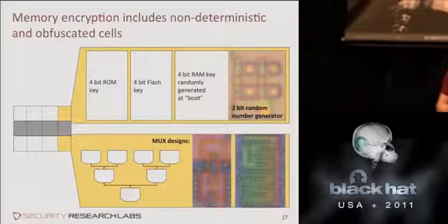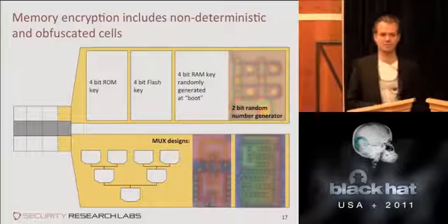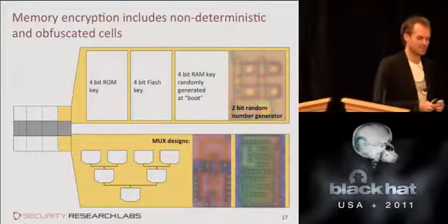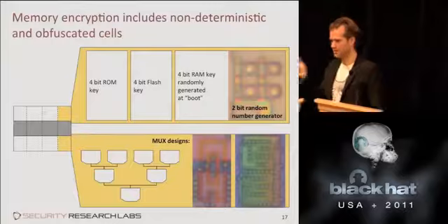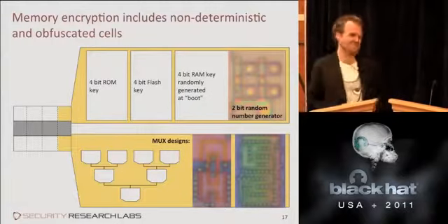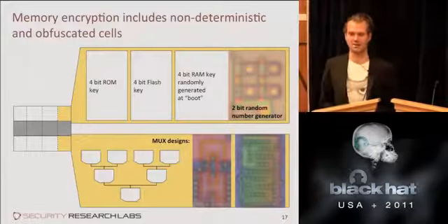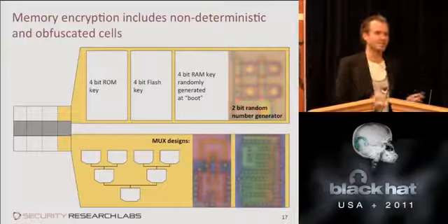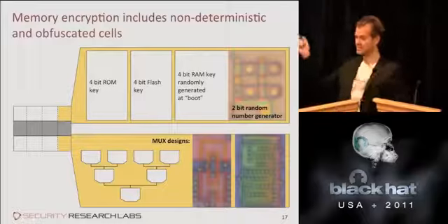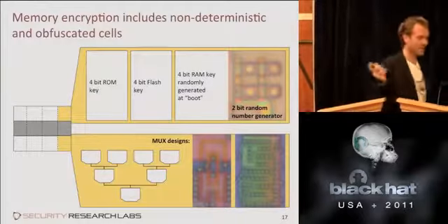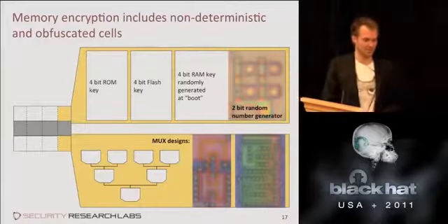And then one last thing to point out here. They did, as I said before, do a good bit of randomization of the gates, or obfuscation of the gates. Usually when you see a simple gate like a MUX in these cases, you can immediately tell what it is. Well, after looking at the silicon zoo, you can, each of you. However, in this case, that's not true. You look at these gates, and they're way too complex for what they're doing. In fact, those two gates shown here on the bottom perform exactly the same function. And just look at how different they are. So they went way out of their way, actually spent extra silicon, just so people could not reverse engineer it very easily.